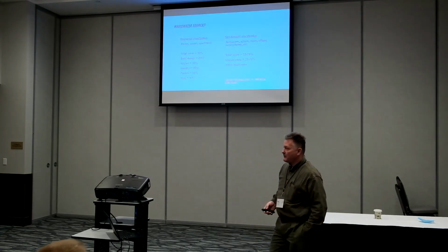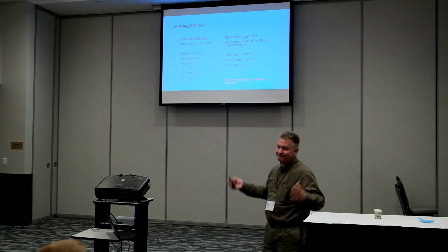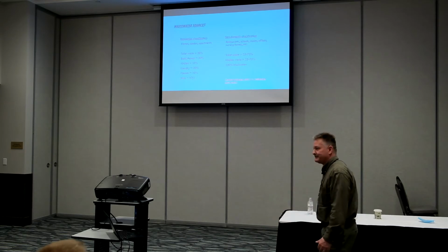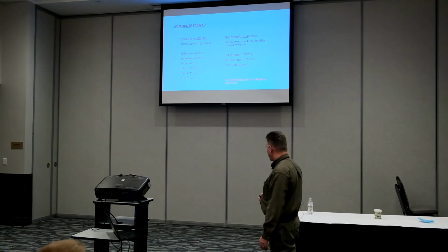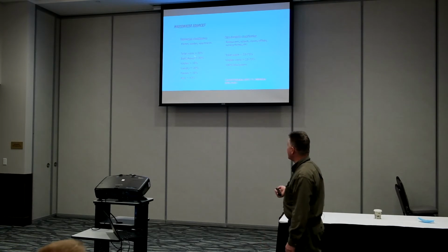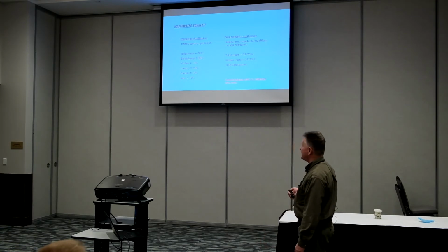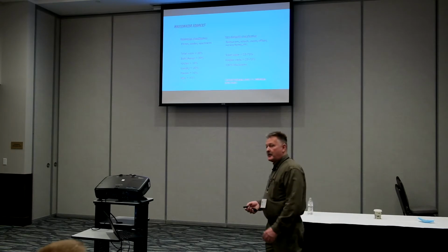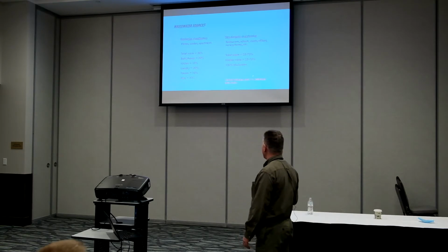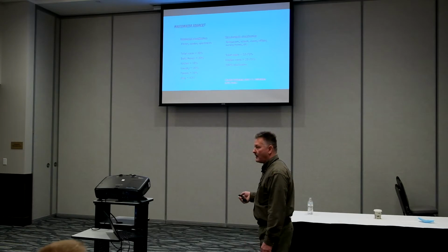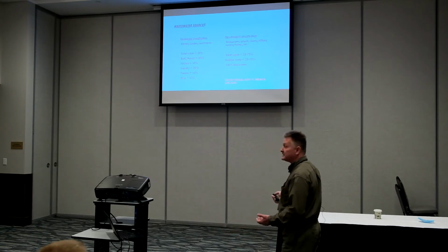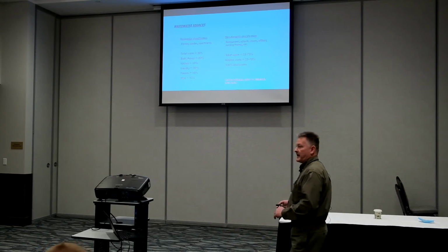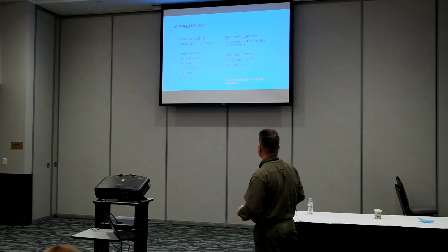So when we look at wastewater sources, residential is textbook. We have decades of research on that. We verify. It's pretty dilute wastewater. We have a lot of gray water mixing in with our black water. Now what we have to be concerned with is commercial gray water versus residential gray water. Residential is actually pretty dilute, and we can dilute down that black water and have a relatively weak waste strength, or what we use as a baseline waste strength.